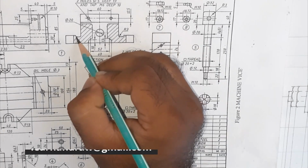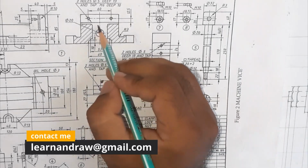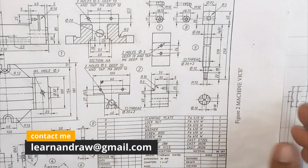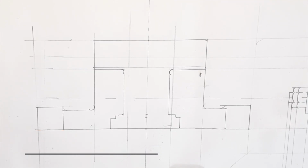Here we have to draw a curve of 13 and 13 mm, and here 3 and 3 mm, and here also 3 and 3 mm. So now this almost completes the part number 1, that is body of the vice in the top view, side view.